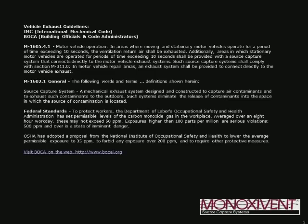This is a resource, and again, this is from the IMC, or the International Mechanical Code, but there's some very important information in here as well. So you can read it at a later date, but a couple of things I'd like to point out. In the first paragraph, it says, in motor vehicle repair areas, an exhaust system shall be provided to connect directly to the motor vehicle exhaust.